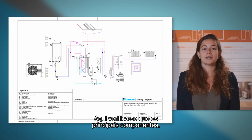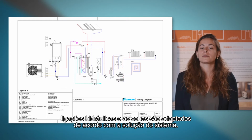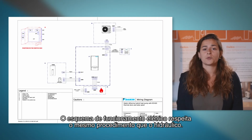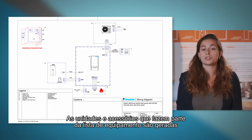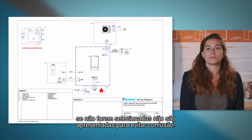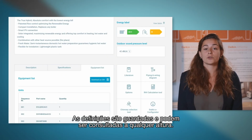Here you can see that the main components, hydraulic connections and zoning, is adapted according to the system solution. The title block contains the installer and customer's name and contact information. The wiring diagram follows the same procedure as the piping. The units and options, which are part of the equipment list, are generated and included onto the diagram. If it is not selected, it is not shown to reduce any unnecessary confusion. You can download and print for use on site. The settings are stored to the lead and can be consulted at any time.